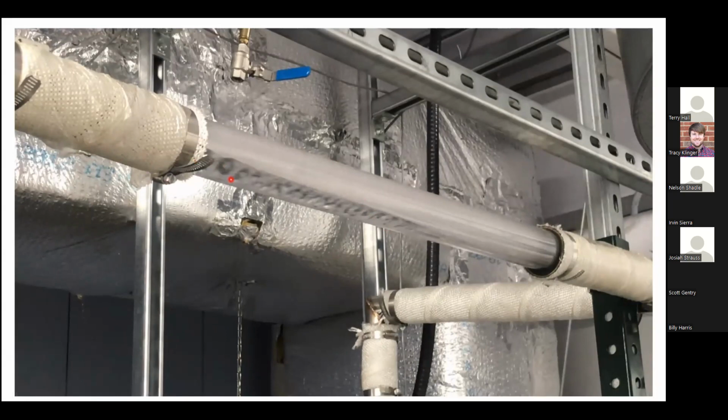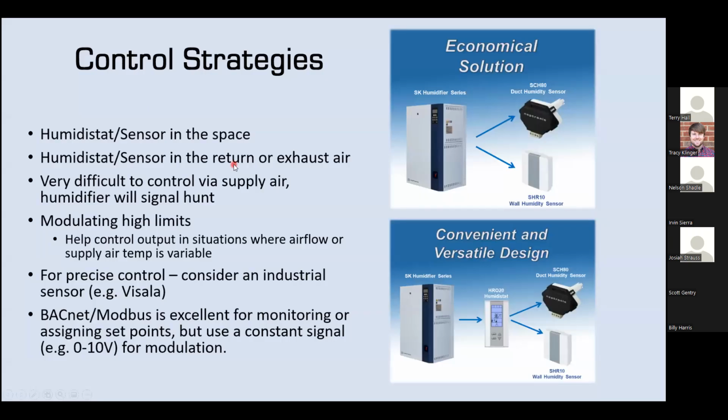It's going to create problems. You're going to start pushing the steam out, and it's going to create condensation, or you're going to push the actual water out into the grid, which can make a mess. So it's definitely important. This is why we say to slope the steam hose as best possible, and we give a guideline of 15%.